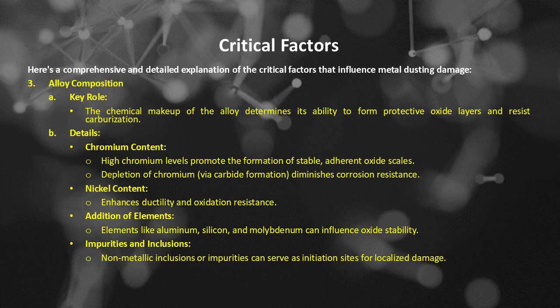The second is nickel content, which enhances ductility and oxidation resistance. The third is addition of elements. Elements like aluminum, silicon, and molybdenum can influence oxide stability. And the fourth is impurities and inclusions. Non-metallic inclusions or impurities can serve as initiation sites for localized damage.